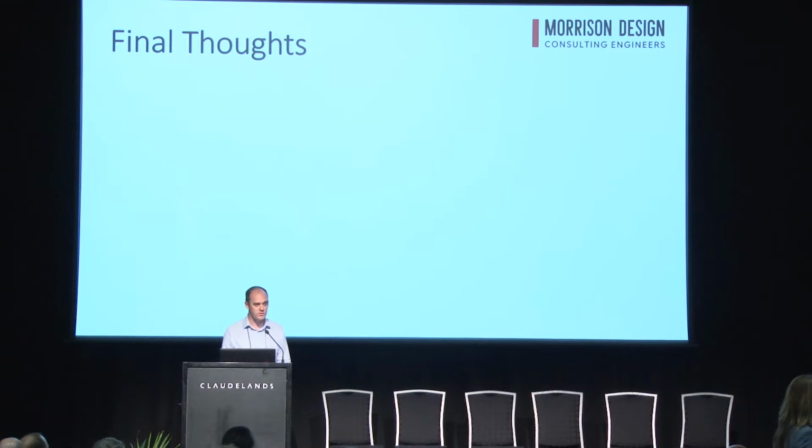6.25 kilonewton slip, I think, is the figure off the top of my head. That's what they're good for. Is that quite conservative, because doesn't it depend quite a lot on the installation? It does depend a lot on the installation, and that has a factor of safety of 2 in it.